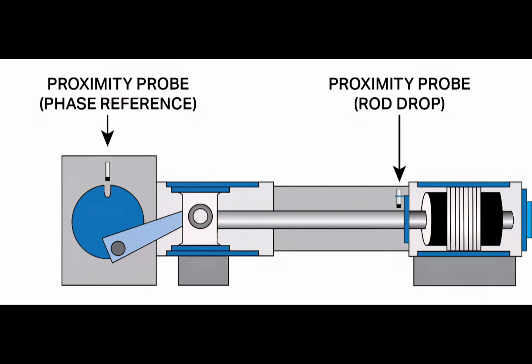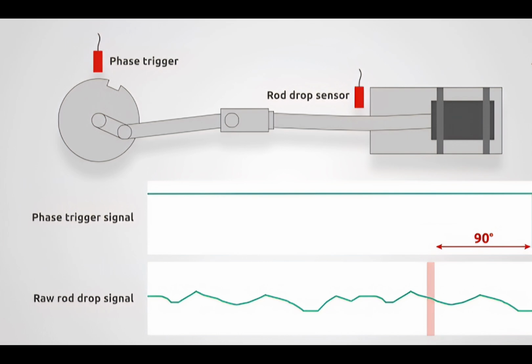In addition to the proximity probe system monitoring displacement, a second proximity probe should be installed at the drive end of the piston to measure the speed and phase of the rotating element. This allows the displacement reading to be taken at the same time and position in the piston rod cycle, which is necessary to be able to accurately trend data over time due to the deflection at various rod cycle stages.